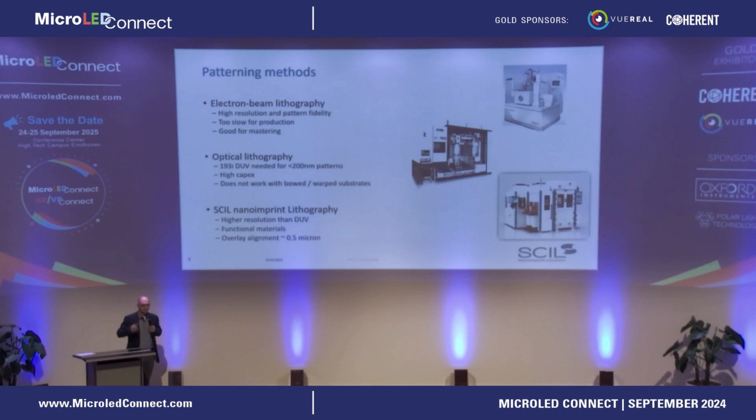For nano imprint, you need one original master. I'll explain later. So we use E-beam and also optical lithography. Optical lithography, ASML tools, have high resolution, but if you would like to go for deep or sub-micron patterns, you have to go for really expensive tools. Think 60 million, 80 million, just CapEx investment, and then you still have to start.